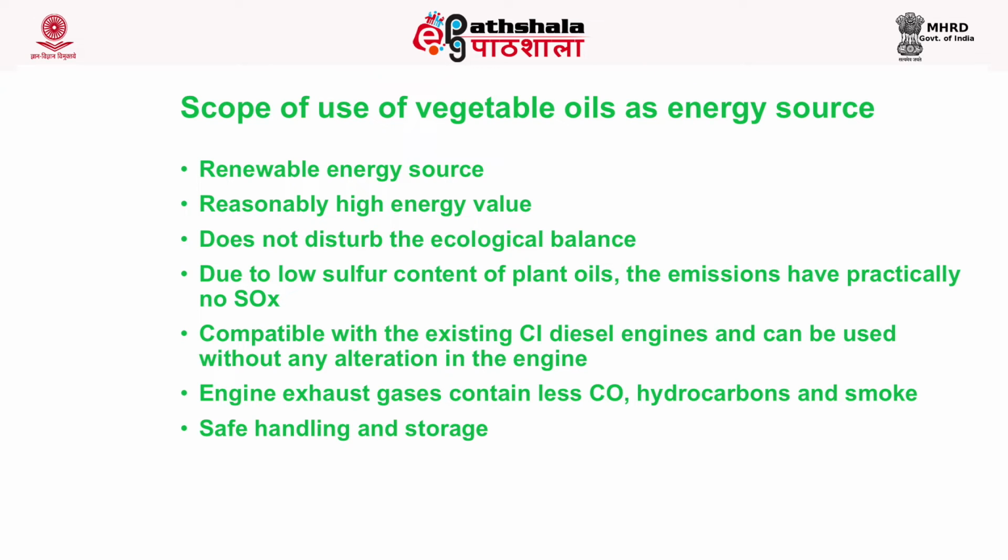Compatible with the existing CI engines. So it can be used in compression ignition engines, that is all diesel engines without any modification. And engine exhaust gases contain less carbon monoxide, hydrocarbon, and smoke. So the molecule of the biodiesel, or oil, contains oxygen, and because of the presence of oxygen, there is less carbon monoxide, hydrocarbons, and smoke along with the emissions coming from the engine.